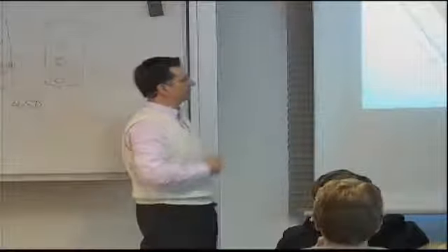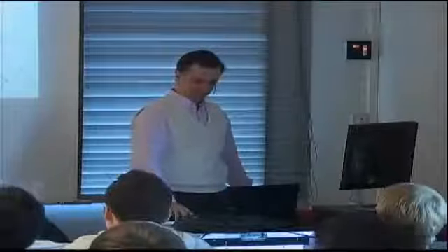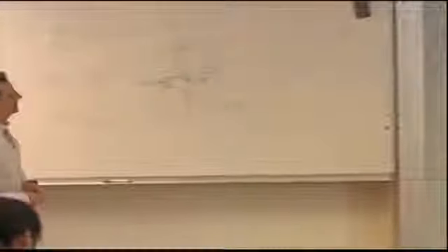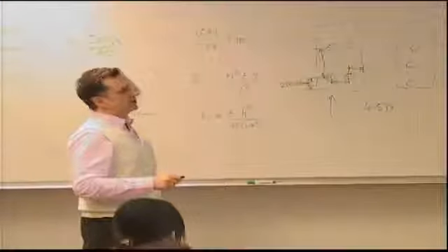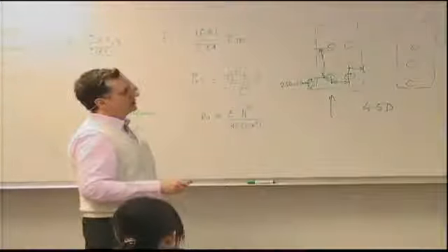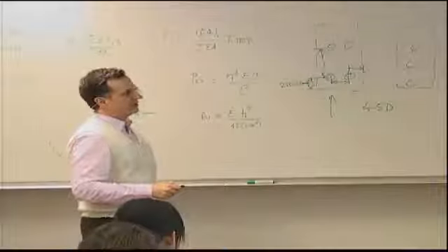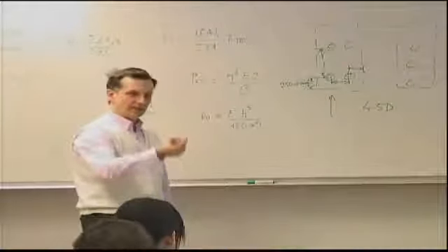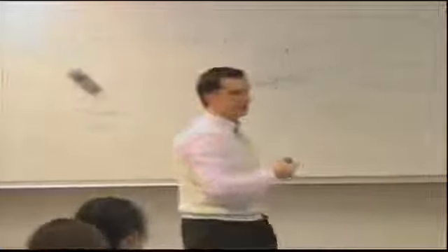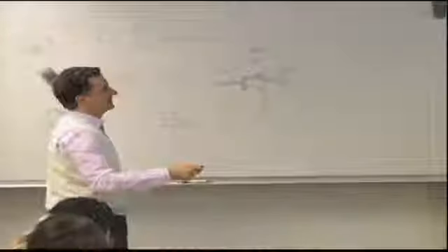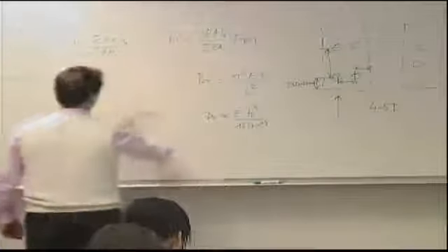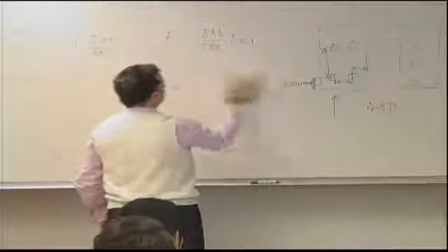Let's take a generalized case with generalized in-plane loads. As a background, the skin takes pressure loads, membrane action, like a balloon. It takes shear loads, and it's interesting, compared to compression, skin also takes compression loads, but only up to skin buckling. Once it buckles, there is some post-buckling capability, and we've done analysis methods, but it's not as good as it is under shear. So if I have a skin under shear, in fact, post-buckling can do extremely well.